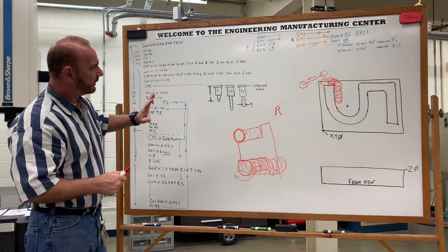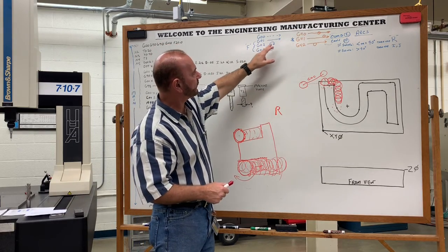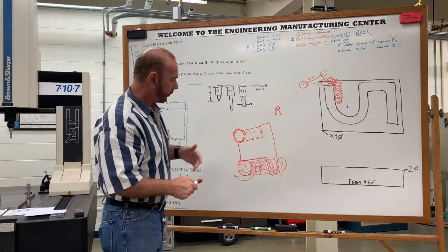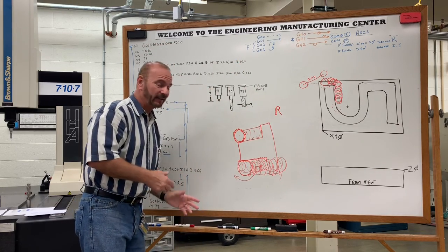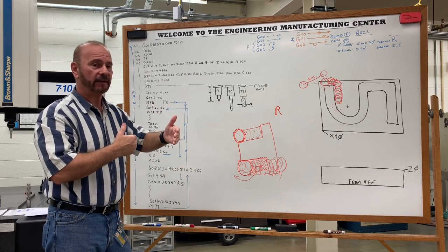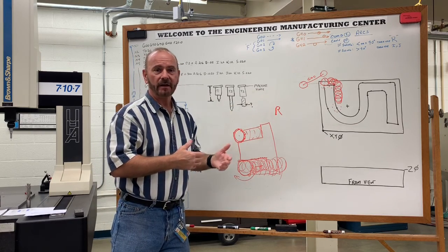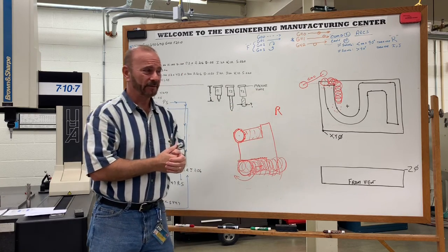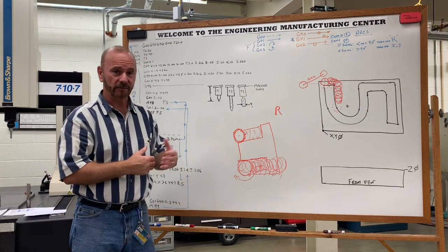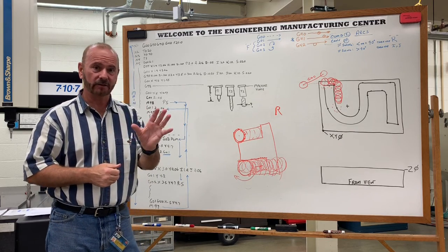The next thing is when the tool is traveling through the material. Remember I said these three moves when it's in the material require that F statement, a feed rate. So what is a feed rate? Well, a feed rate is exactly what it implies. It's a rate of feed that the cutter is going to be traveling through the material, and that's based on a formulation that we have. So the best scenario that I can give you guys about metal removal rates and feed rates is one called cars, trucks, and roads, because it's kind of easy to relate to.